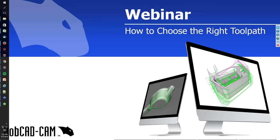What we're actually going to be doing today is covering how to choose the proper toolpath. We're going to go across a wide spectrum of different options, because every toolpath is specific to what it can do. Some toolpaths are just pocketing styles where they pocket in and out. Other ones have options where you can do a trochoidal type of cut or a planar style cut.